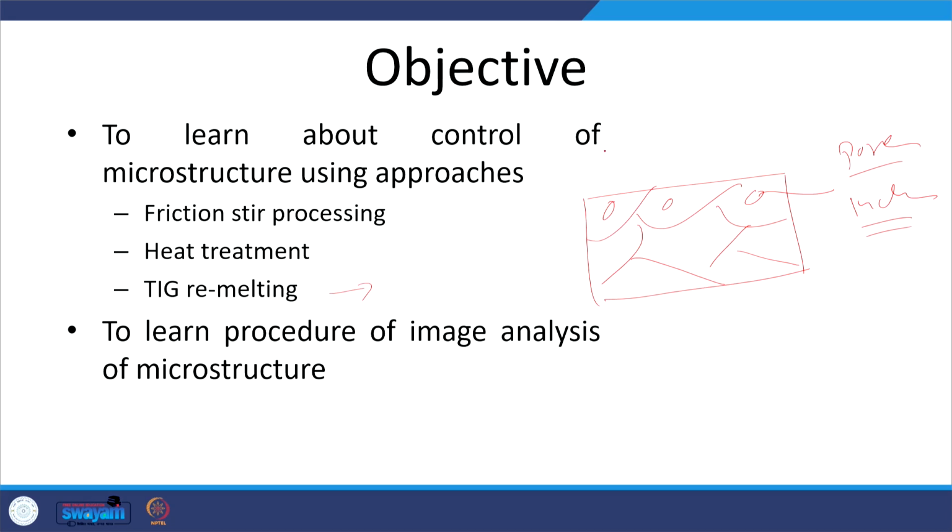So, when we apply controlled heat for melting the near surface layers with the help of TIG, impurities in the form of inclusions will come up to the surface, and the porosities will collapse. What happens after the solidification? Since the cooling rate experienced by the molten metal produced through the TIG arc is higher, the higher cooling rate during solidification results in a refined grain structure. Even if it is a transformation hardening metal, this kind of remelting can also produce hard constituents at the surface layer.